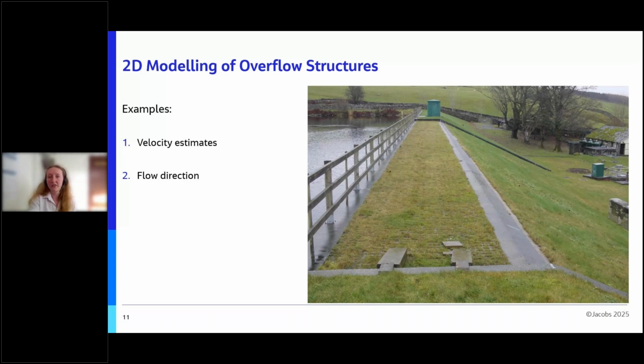A second use of FM2D for solution design at reservoirs is when there is water spilling out of the chute onto the dam and threatening its integrity that way. In this example, we could use FM2D to understand flow direction and mechanisms to help inform design of bunds to route the water back into channel. We do have a goal to integrate 2D domains into reservoir flood routing models on more sites, as we know Flood Modeler 2D has this capability.